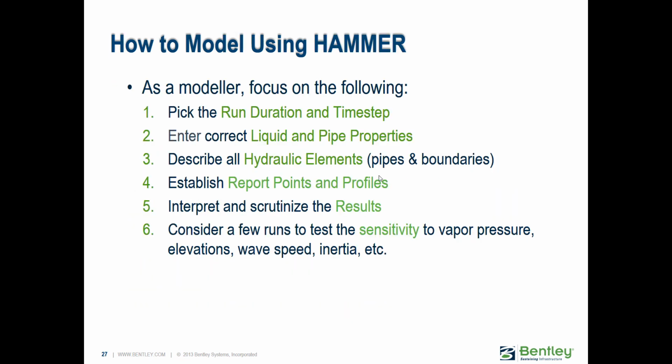So how to model using Hammer? Things to focus on. This is the basic process here. First you decide on your simulation duration and the calculation time step. You enter your liquid properties, your pipe properties, basically your initial conditions. You get all that set up.